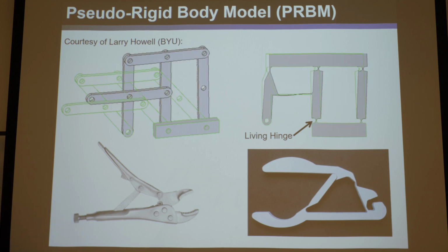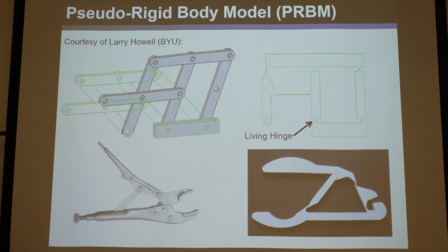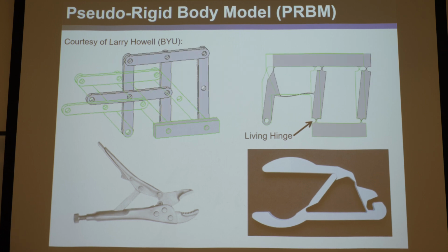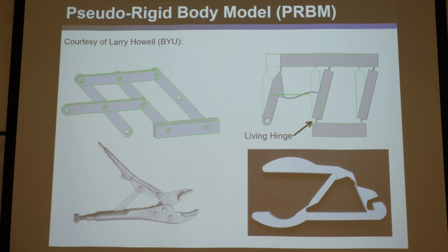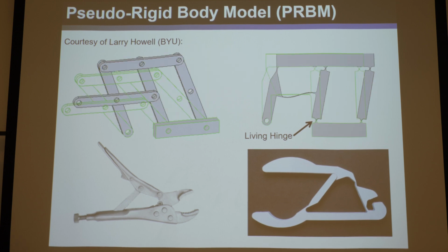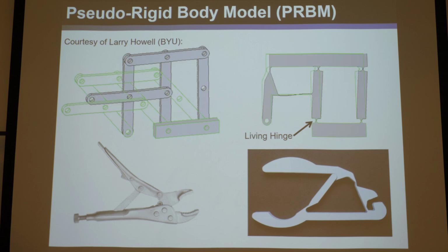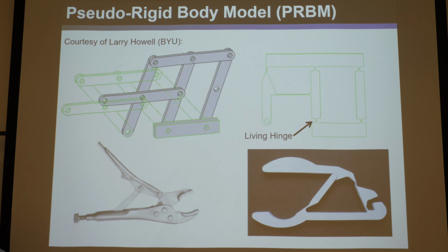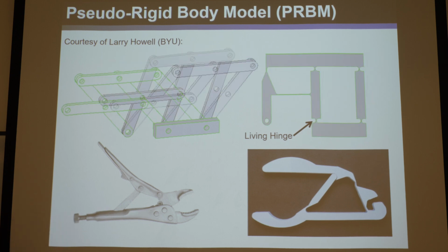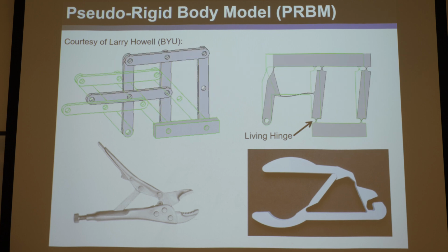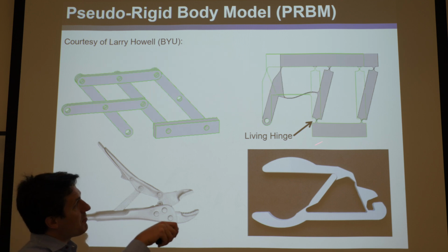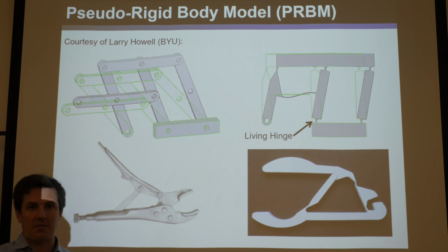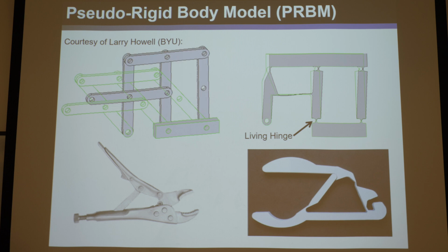And so what Larry did is he basically said, well, let's use hundreds of years of this mechanism theory for rigid mechanisms, allow designers to design things with rigid mechanisms that move the way they want, and then allow them to put the torsional joints where they want to have the stiffness they want, but then convert that into a compliant form using pseudo-rigid body models, so you have a fully compliant mechanism that essentially does the same thing. Okay? So that's a way to simplify things.